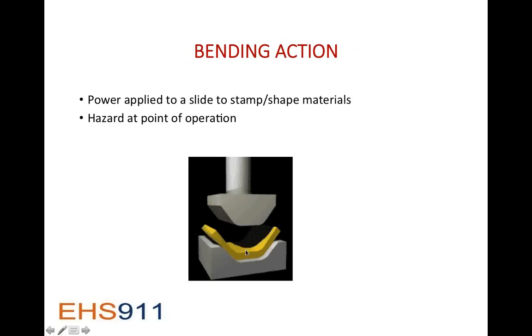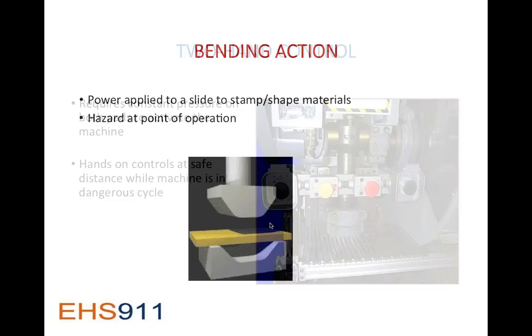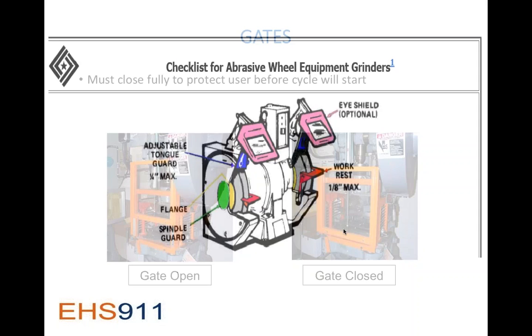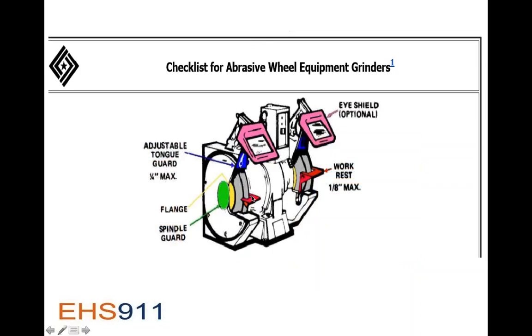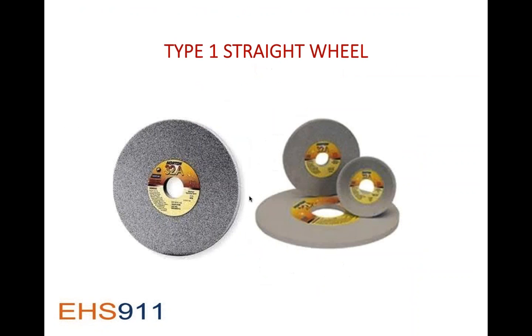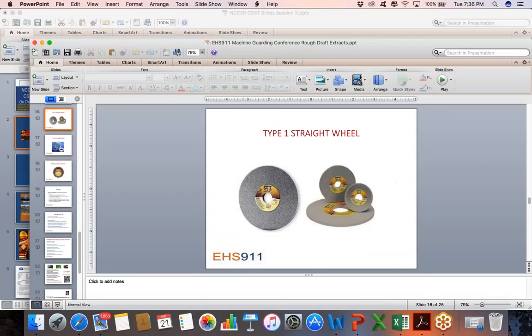Where this press is bending, that's the point of operation. Where this die is hitting the piece of equipment that it's molding, there's your point of operation. And where there's a grinder, where you put whatever you're grinding and it hits the grinder, there's your point of operation. So you get where I'm going, folks? It's wherever the tool meets the stock. Okay, so let's see, point of operation, hand switches, right?